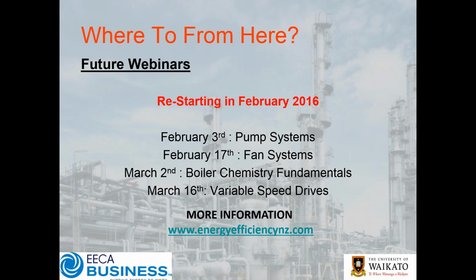I.e. it's going to use less air, but then also does it clean my bag better? And these are all the considerations, and as you rightly point out, it could lead to a better load on your ID fan. Now, it could do one of two things: either reduce your energy bill, or if that's your bottleneck, free up capacity, which is where you can really make some money. So it really does come back to, you need to do the proper review of the system.